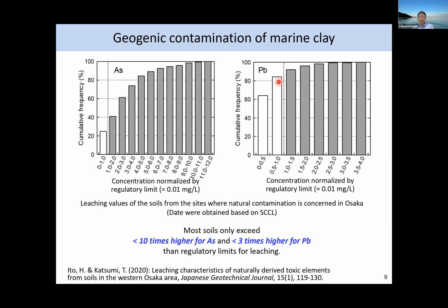And if we look at the lead, the concentration levels are much lower compared to the arsenic. Almost all the marine clays are less than 3 times larger than regulatory values. So we'll say, yes, we have marine clays exceeding regulatory limits, but most of the soils only exceed 10 times higher for arsenic or 3 times higher for lead than the regulatory values for leaching.